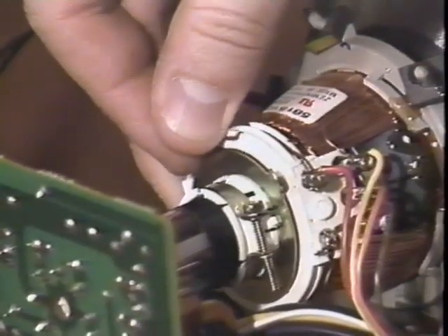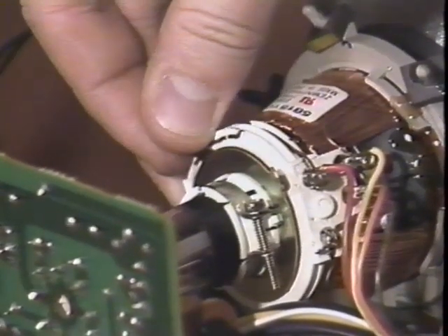First, make sure that the display area is not tilted either to the right or left by moving the yoke around the neck of the CRT. This is called the Raster tilt adjustment. Next, you must center the display area in the middle of the physical area of the screen using the centering magnets located on the yoke. Once this is done, perform the Raster geometry adjustment.